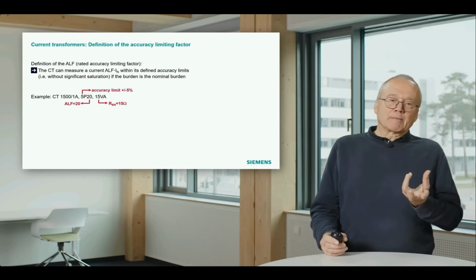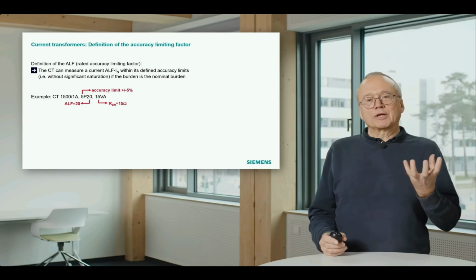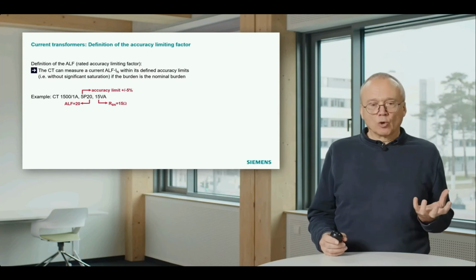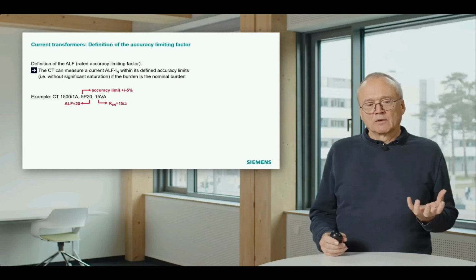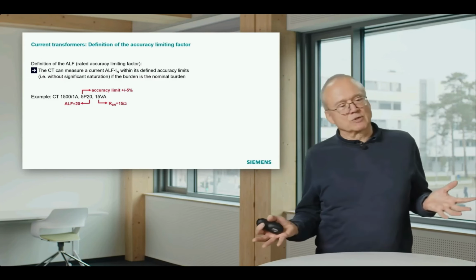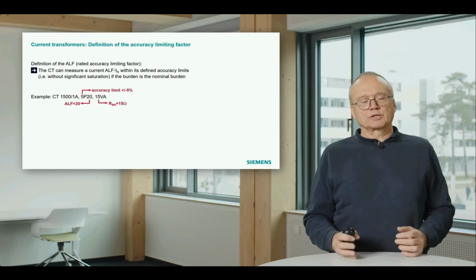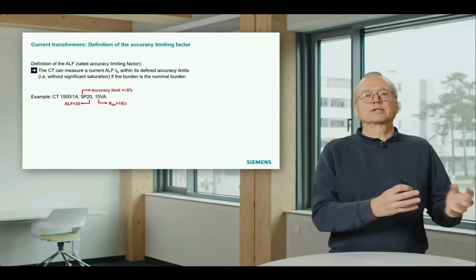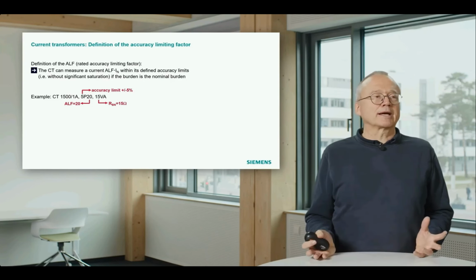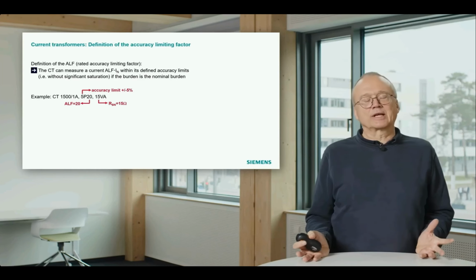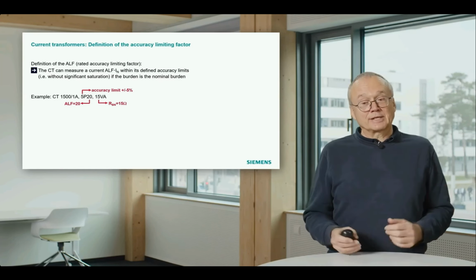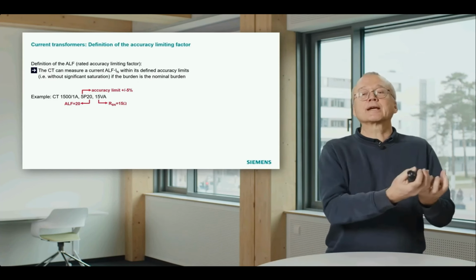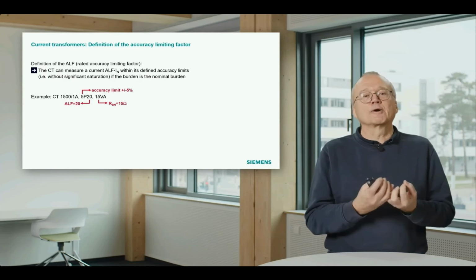Now if we do the dimensioning, we have to take into account that the actual burden we have may be lower. What you sometimes have is a very old current transformer which was at the beginning of its life still connected to an electromechanical distance relay, which had a pretty high burden, because these old devices had to take energy from the current transformer for operation.